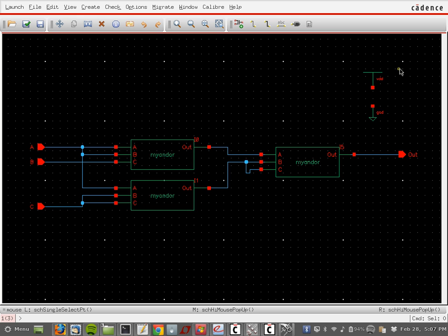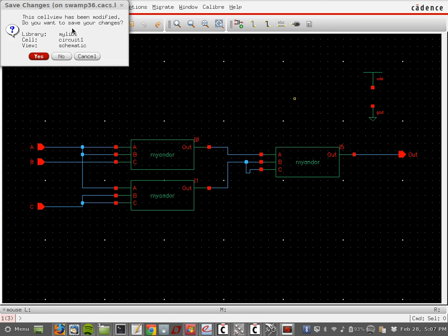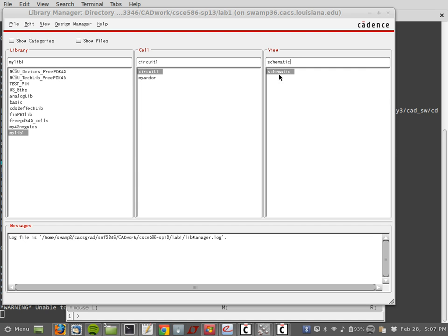Otherwise, they wouldn't show up under global sources in the ADE simulator. So make sure you have VDD and ground like that. If you have them already in a schematic, like in a transistor schematic, then you don't need to put them. But there need to be at least one VDD and one ground like that for a circuit to work. That's just something I forgot to mention last time.